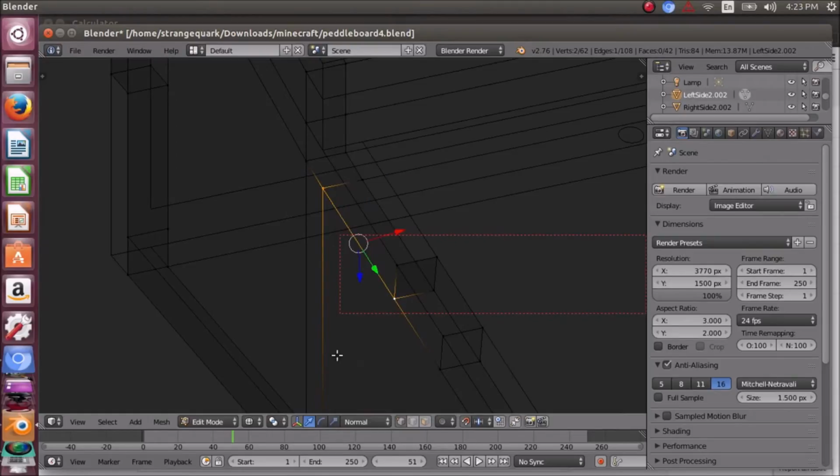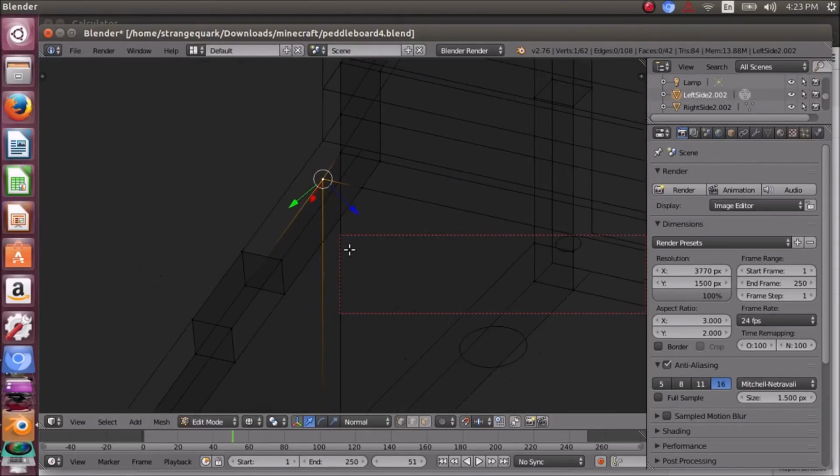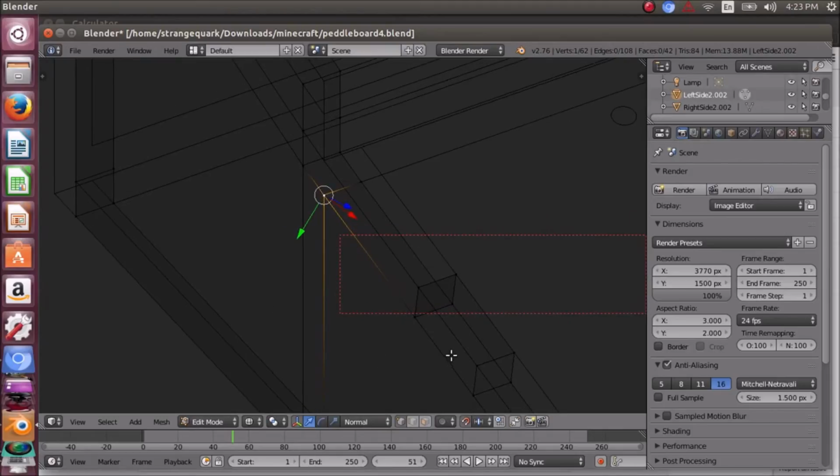The problem we can see here is that if I choose the normal just for the vertex alone, I don't have any one of these axes moving along the line. So if I wanted to extrude or project on this line, you want to have the transform orientation recorded for the line itself.